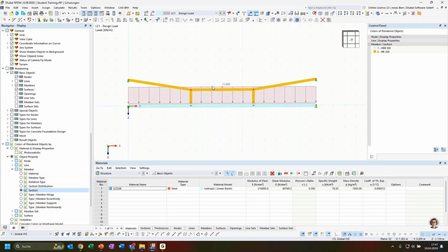Of course, the stiffness of the support depends on the stiffness of the nodal supports here at the ends, also on the truss member stiffnesses and the length and so on. And if these wouldn't be fixed in the X direction, they would just move towards each other, and I wouldn't have any additional supports provided by this upper substructure here.